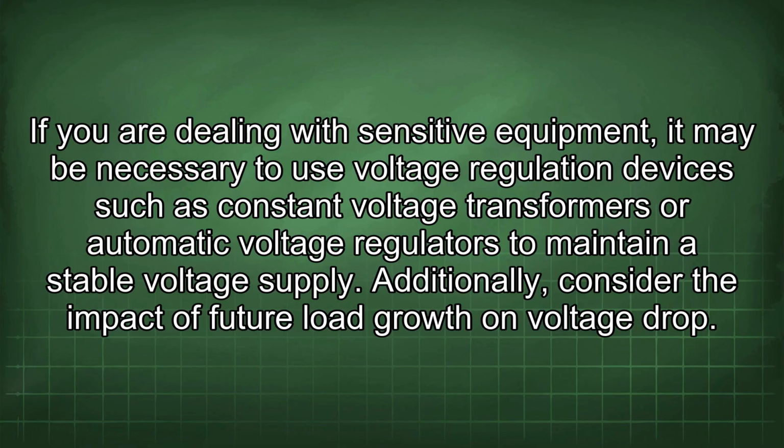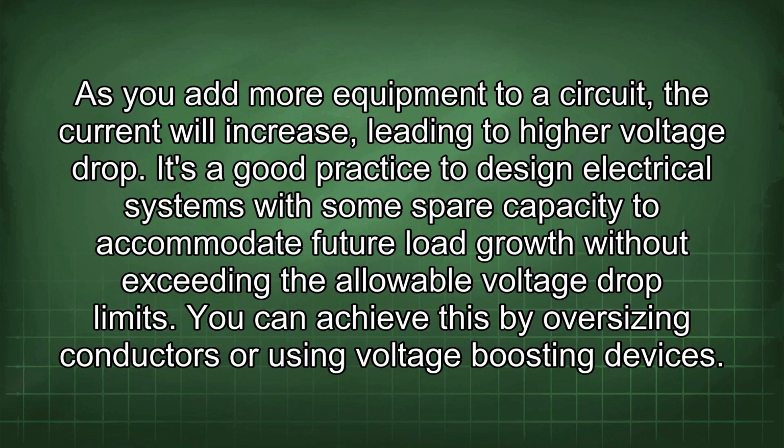Additionally, consider the impact of future load growth on voltage drop. As you add more equipment to a circuit, the current will increase, leading to higher voltage drop. It's a good practice to design electrical systems with some spare capacity to accommodate future load growth without exceeding the allowable voltage drop limits. You can achieve this by oversizing conductors or using voltage boosting devices.